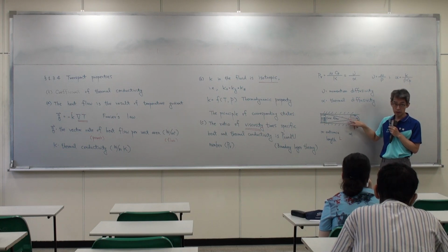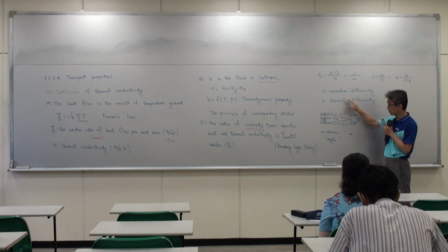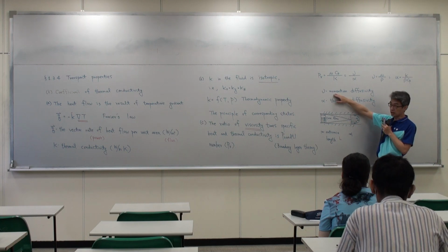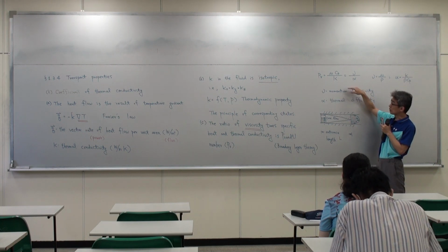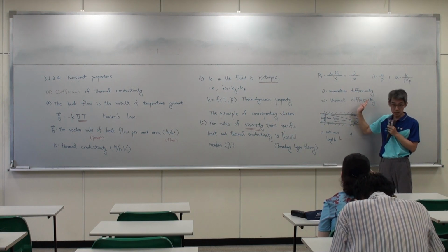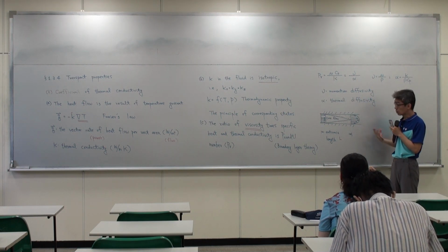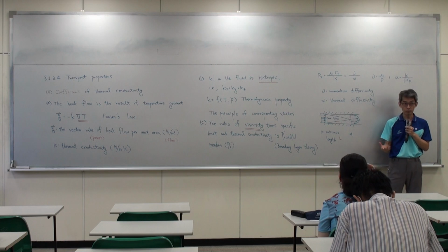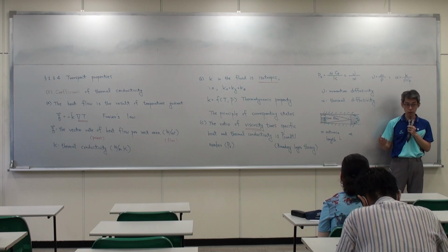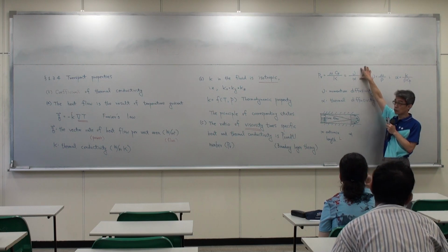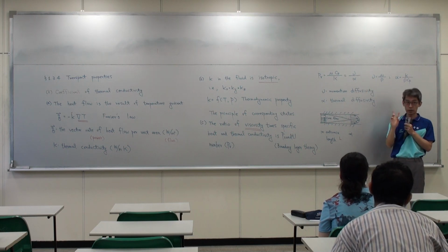The momentum boundary layer is influenced by the dynamic viscosity. Similarly, there is a so-called thermal boundary layer, which is influenced by the temperature of the neighborhood. So the Prandtl number is basically used to compare these two boundaries.